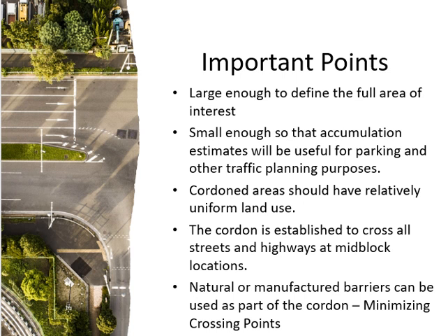And in front of Isa Town we have Lec4.6, which is not so commercial. So if you make the boundary too big, you will include Lec4.6 as well. Now you have a commercial area and a residential area in the same boundary. This will not give you accurate data because there are too many things happening inside the area. So you have to keep the boundary so that you have only one activity inside the area.